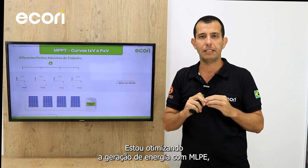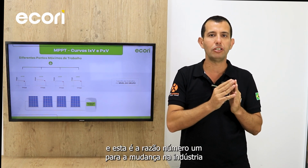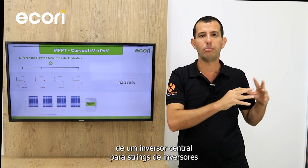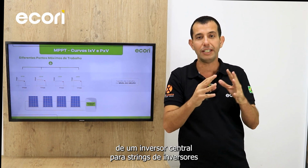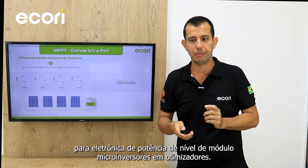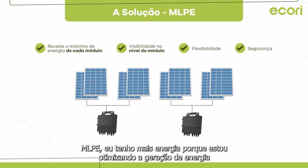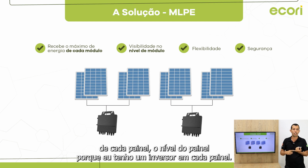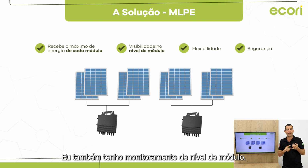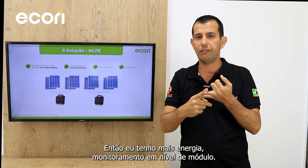I'm optimizing the power generation with MLPE, and this is the number one reason for the change in the industry from central inverters to string inverters to module level power electronic microinverters and optimizers. When I have MLPE, I have more energy because I'm optimizing the energy generation from each and every panel, the panel level. Because I have an inverter on every panel, I also have module level monitoring. So I have more energy, module level monitoring.